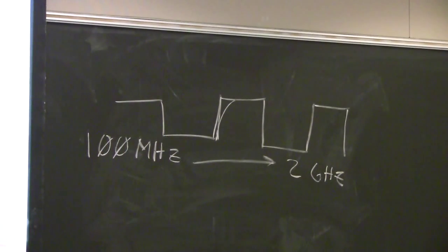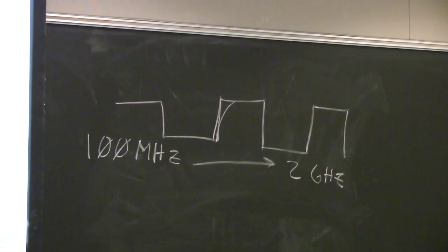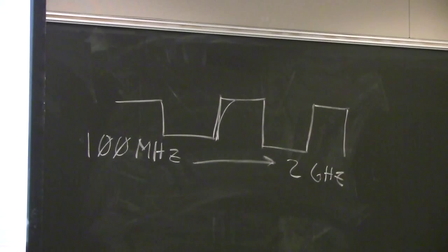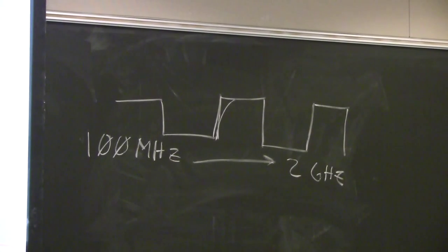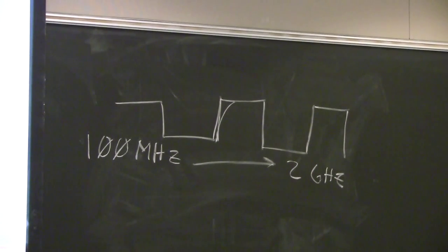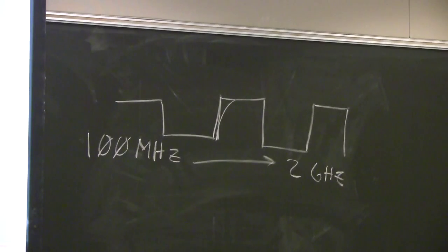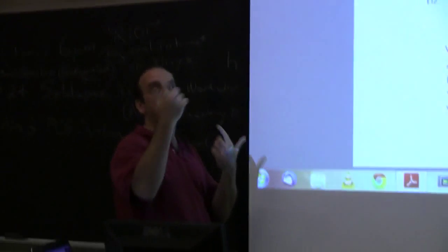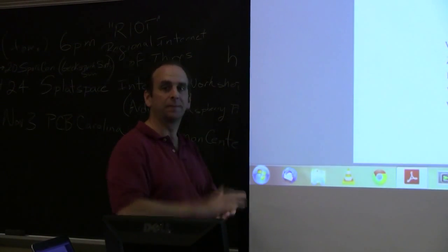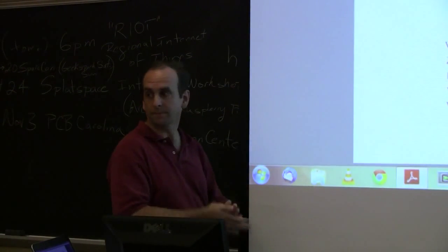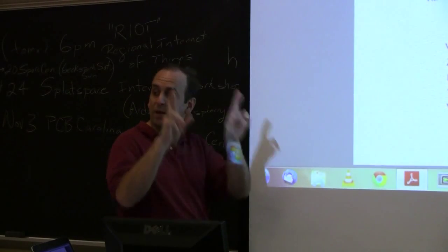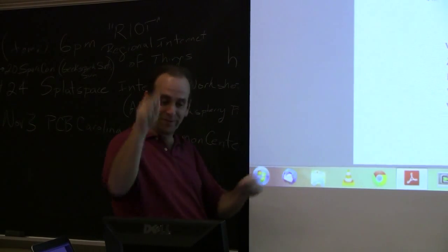So yeah, you have to manage frequency. You have to say, where am I spewing, what's good or bad about that, and who else is trying to get me? If I'm doing my stuff, fat and happy, and you build a radio transmitter next to me and blast this high frequency into my circuits, I'm going to be upset. EMC is like a lawsuit. EMC means I don't come over there and mess you up, and you don't get to come over here and mess me up. So we need to stay apart. So you have to manage frequency stuff. That's what shielding is for. Or keeping your fingers crossed, or just a crap load of ferrite beads and copper tape.